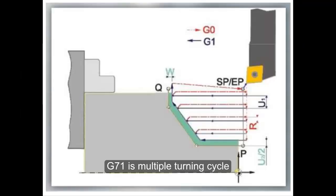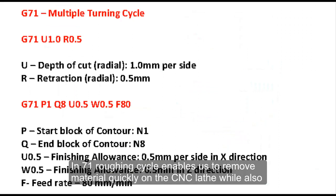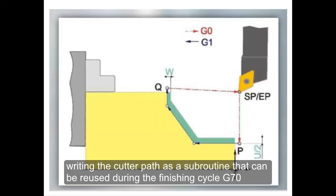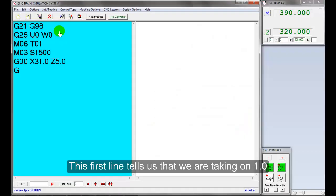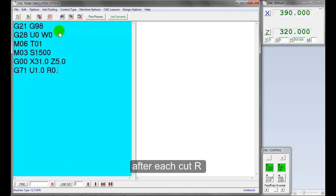G71 is multiple turning cycle, also known as stock removal cycle. G71 roughing cycle enables us to remove material quickly on a CNC lathe while also writing the cutter path as a subroutine that can be reused during the finishing cycle. This first line tells us that we are taking 1.0 mm cuts, U, and the tool is retracting 0.5 mm after each cut, R.